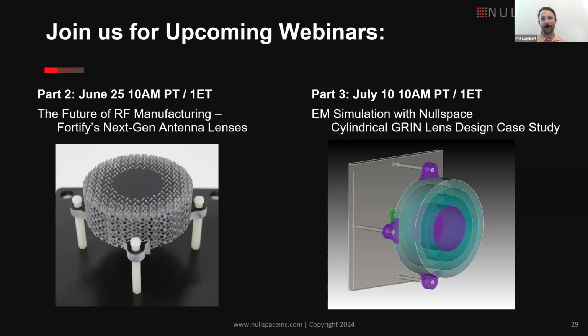If we were to think about the polymers, we can make available, and it's available on our website, the material technical specification for the Radix materials, and it does have an HDT of around 76, for the lower of the two pressure cases. But we've been doing some extended thermal analysis with our partners at Rogers that suggests that long-term exposure of about 125 C shouldn't impact the dielectric performance of the materials.